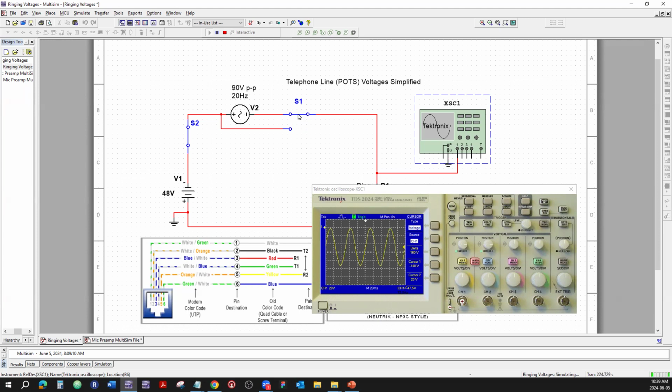So, sir, that's what the AC volts are for? That's for ringing. Yes. So you need 90 volts to ring a phone? 90 volts minimum, yeah, to make the phone ring. And that comes from the old days that you actually needed that voltage to make those transformers active and start ringing those couple of bells that were mounted on the wall.